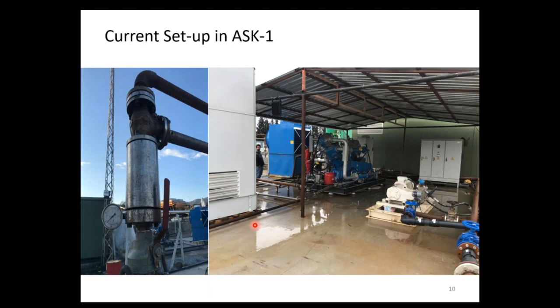When you compress this NCG, there's a certain amount of vapor under pressure. Some of it becomes liquid, and that liquid, with some CO2, some H2S, could be very dangerous, highly corrosive. For that, most of this compressor's internals, like piston and liner, everything, is special ceramic coated. And this is our engineering design.